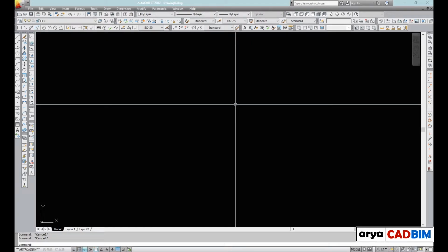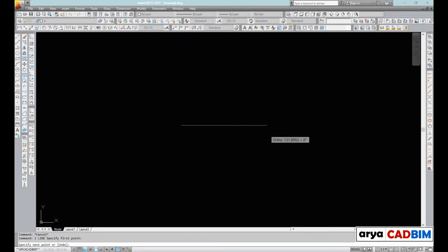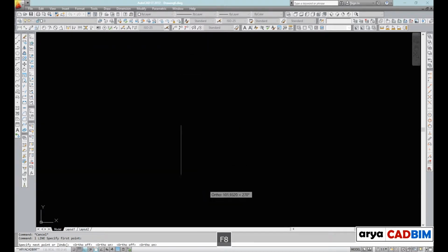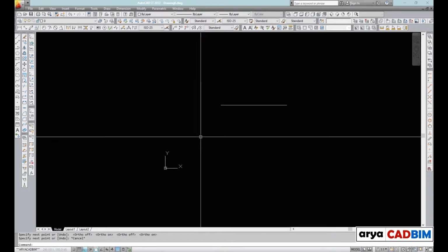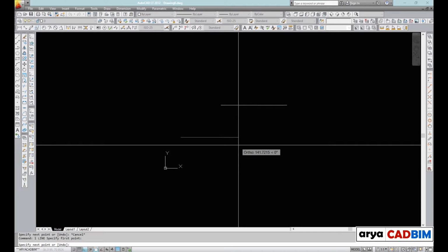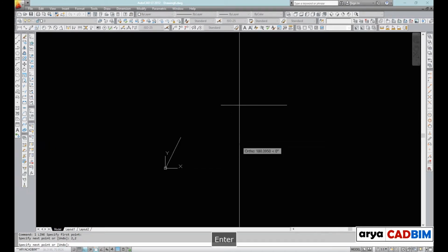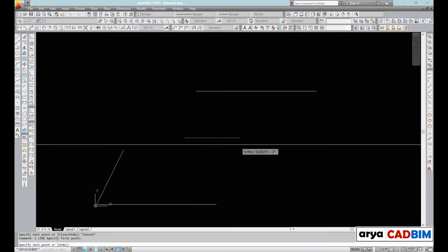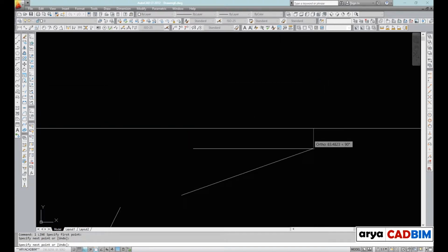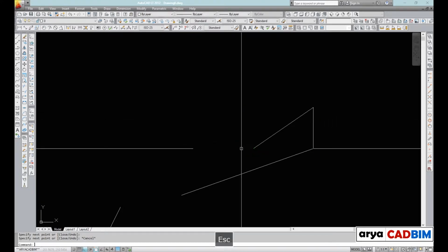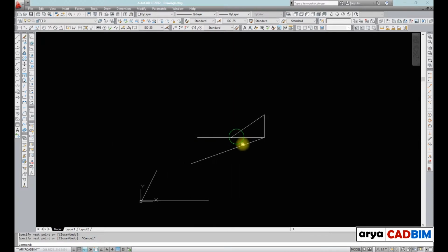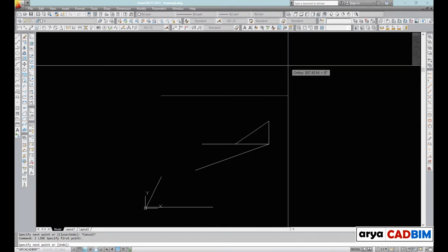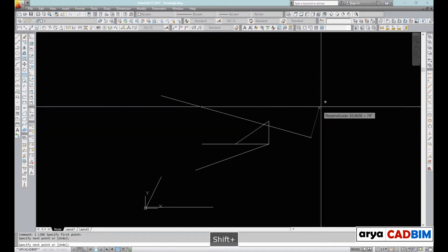You can turn ortho on and off at any time during drawing and editing. Ortho is ignored when you enter coordinates or specify an object snap. To turn ortho on or off temporarily, hold down the temporary override key, which is the Shift key. While you use the temporary override key, the direct distance entry method is not available.